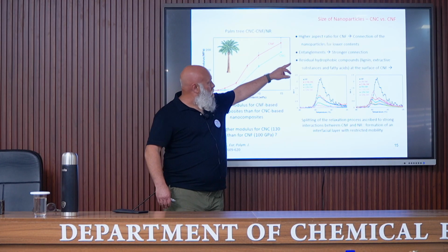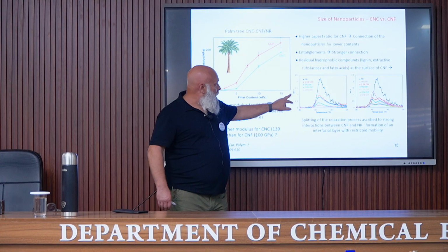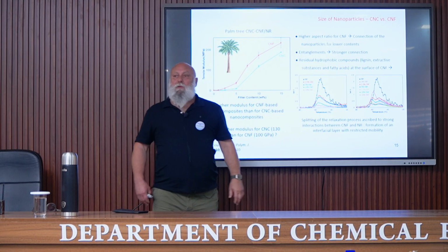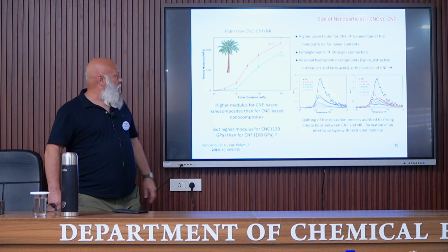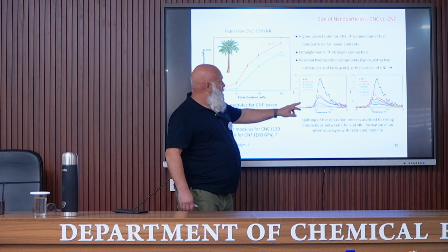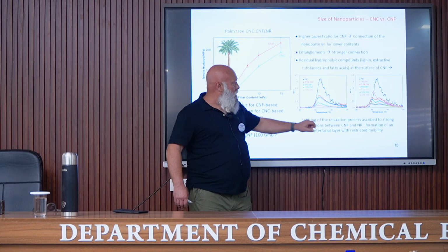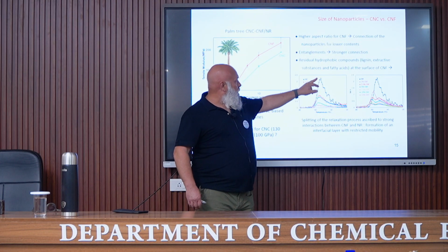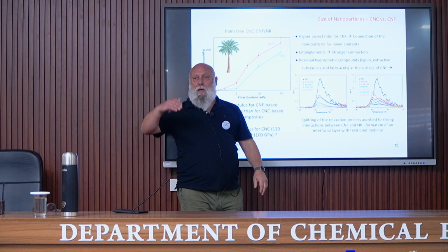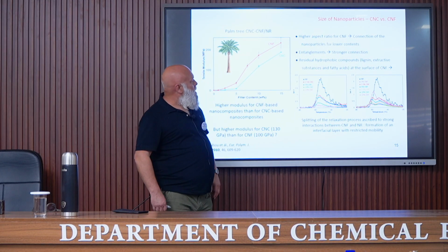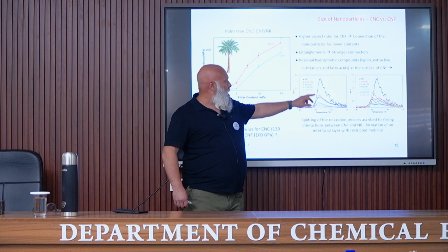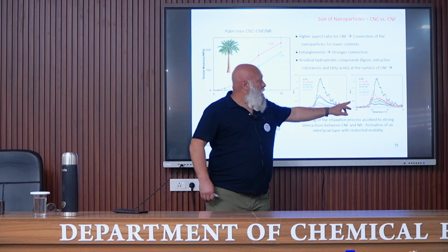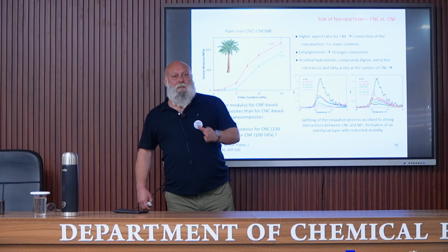I will just show you results for this last point. You have here the loss angle as a function of temperature. It is dynamic mechanical analysis for composites based on nanocrystals and nanofibrils. For the pure matrix, we have a high damping, high loss factor, and it progressively decreases when adding nanocrystals. In the case of nanofibrils, you can see that it's different.